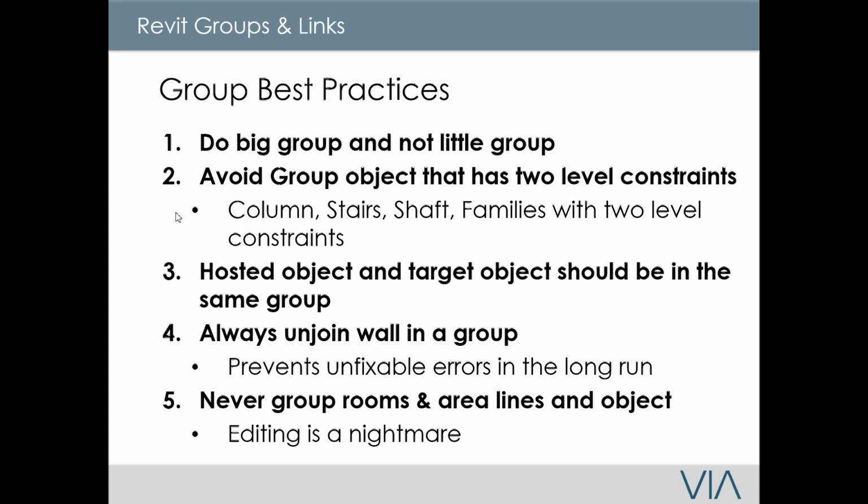So in this slide, I just want to talk about the best practices. Typically, when you work on groups, I do recommend you do a big group and not little groups. What I mean by that is when you have kitchen layouts, washroom layouts, bathrooms, etc., I typically like to do it as a massive group, not those little tiny ones. The reason is that it keeps your files very clean, okay?